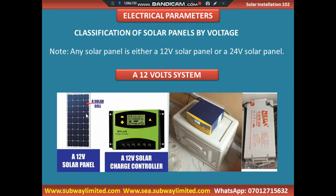If you are using a 24 volt solar panel, it will blast this charge controller, because it's not a 12 volt solar panel you are using with it. So we will destroy this solar charge controller. Equally, it will destroy this particular inverter that you are having here, and it will equally destroy this battery.